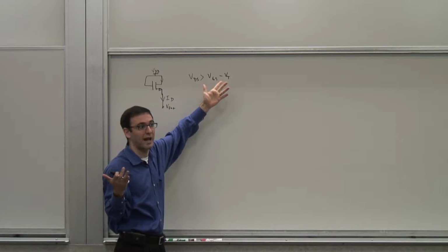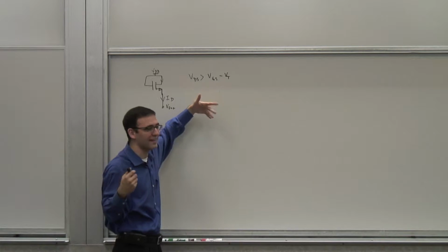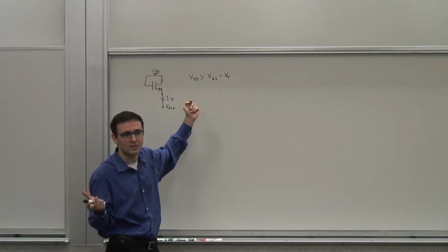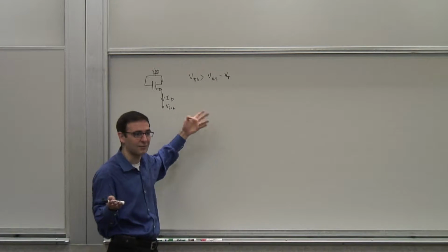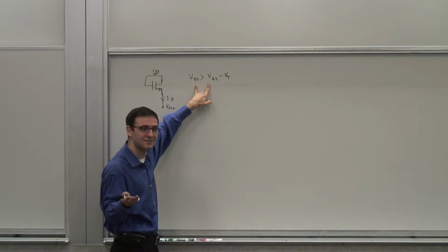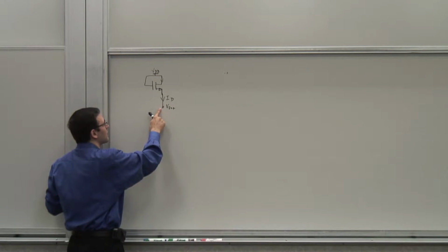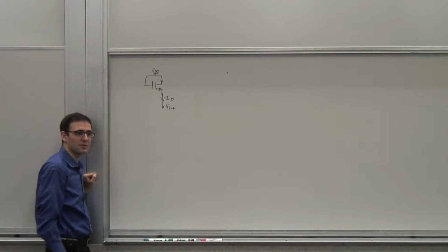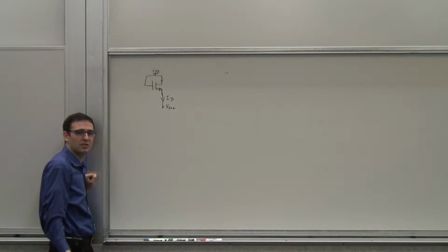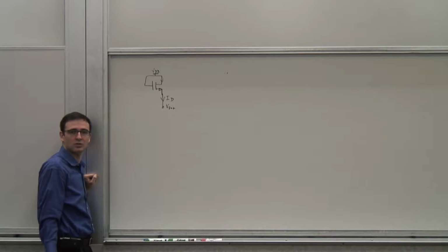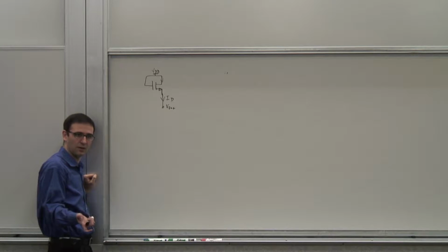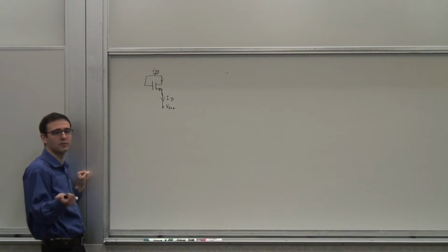You can have a transistor with negative VT, although we don't often use them in circuit design, and they're not very good transistors, but you can have them. And if that's the case, then this will not be in the pinch off region. So it's either in pinch off or it's off, right? Because it could be off. If V out is at VDD, for instance, what is VGS? 0, right? It's below VT. So it's either off or in pinch off. So it does not enter triode for positive VT.